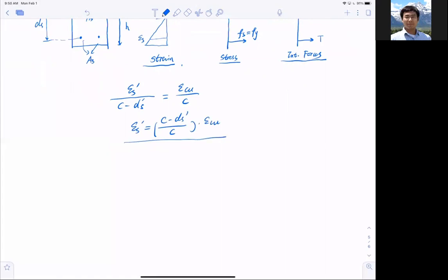Now, compression force from the concrete equals Cc. Before, it's just 0.85 f prime c and beta 1 c, which is a and b. And now it's still the same, it didn't change. In addition to previous cases, I now have a compression force from the steel, which is As prime, the compression reinforcement, multiplied by the stress in the steel on the compression side, Fs prime. But listen to me, ladies and gentlemen, because we need to care for the concrete now. This is the added part.